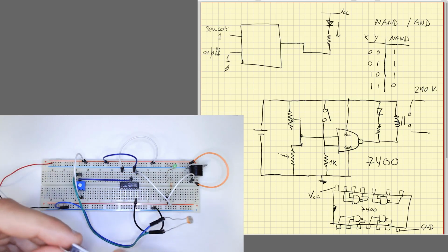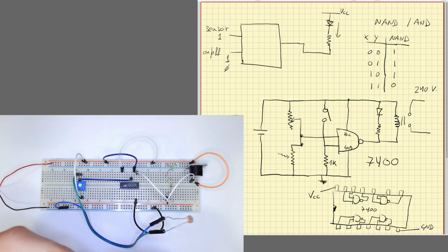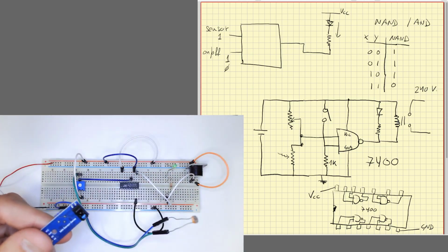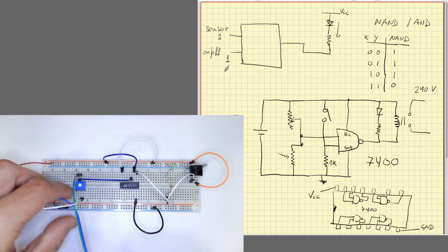So we will normally use a sensor already made. This one detects light, but the light reflected, so it detects when the sensor is in proximity with something. It's useful to build small robots, for example, line followers, or to detect some kind of moving parts when they cross across the sensor. The good thing is that because it uses infrared light, it does not depend on the ambient light actually. It generates its own light. So we are going to substitute then our sensor.